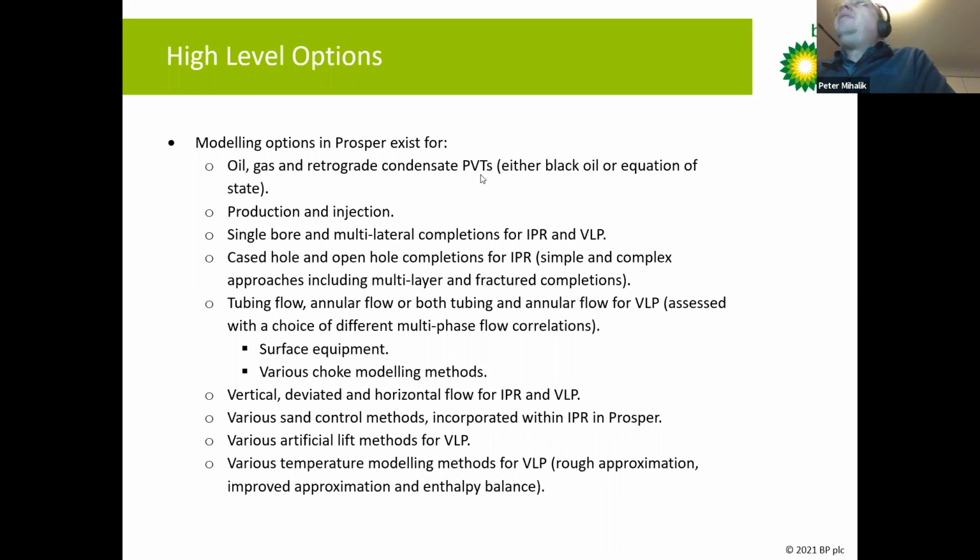The PVT modeling, well, you can either do that with a black oil correlation approach or an equation of state. Most of the time, black oil modeling is quite appropriate, but if you have particular retrograde condensates or volatile oil systems, then maybe a black oil PVT model is just not quite good enough. Sometimes you need to enter an equation of state instead. But we'll just be looking at a black oil model today. But we will assess which black oil PVT correlation is going to be suitable for the fluid that we've got.